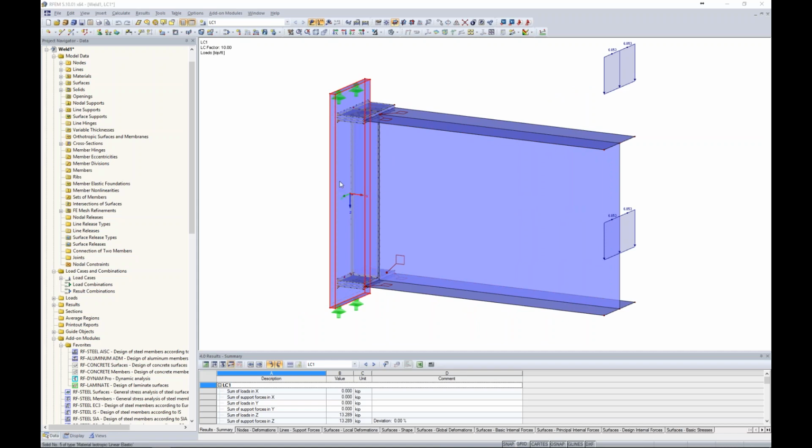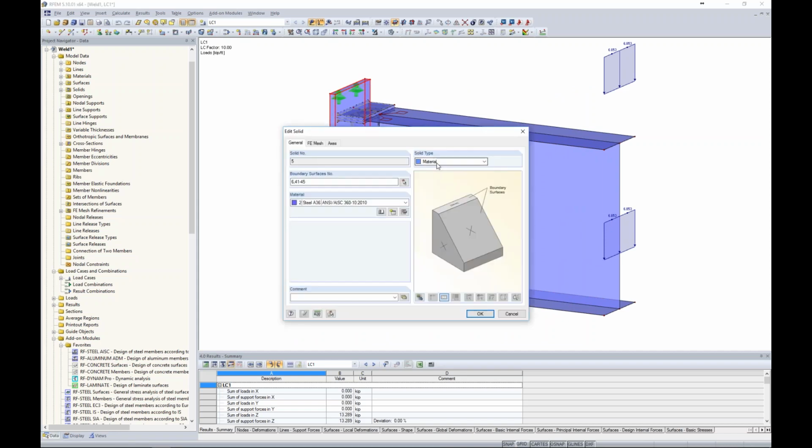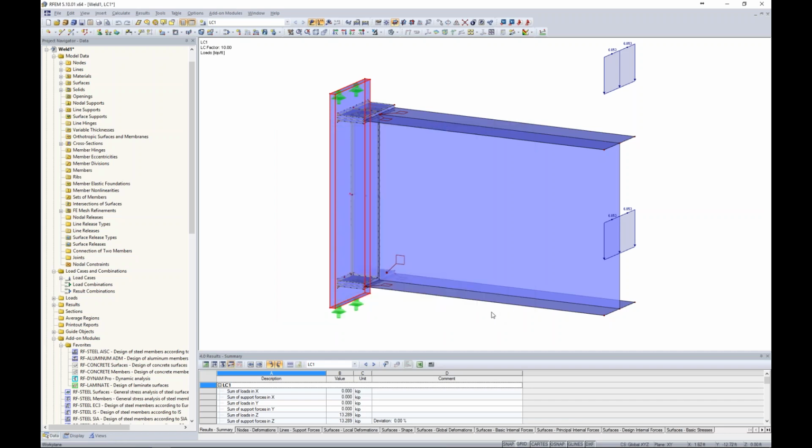When I take a look at this plate element, I no longer change this to a contact surface or contact solid. It's just a typical 3D solid with a material set within the depth of steel A36. So this is just a 3D element within our program RFEM. Now, all of those requirements for boundary lines, same integrated objects, those go out the window for a typical solid element. That's not required for typical solids, just only for contact solids.